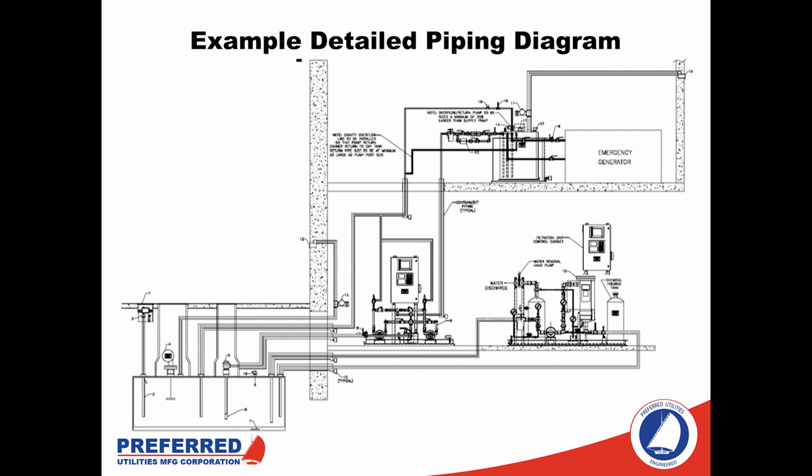So when we talk about a traditional fuel oil system, it's going to be similar to the setup we see here. There may be more day tanks at the generators, multiple generators. There may be multiple main tanks even, but typically we're going to have a large amount of fuel stored in one place, and then that fuel is going to be moving to another place to serve the generator itself. And the bulk of what we're talking about today is going to be applicable primarily to emergency generators, as that's the application that we're seeing in mission critical facilities. Some of this could also be applicable to fuel systems that serve boiler plants, but that's not the primary goal of this presentation today.